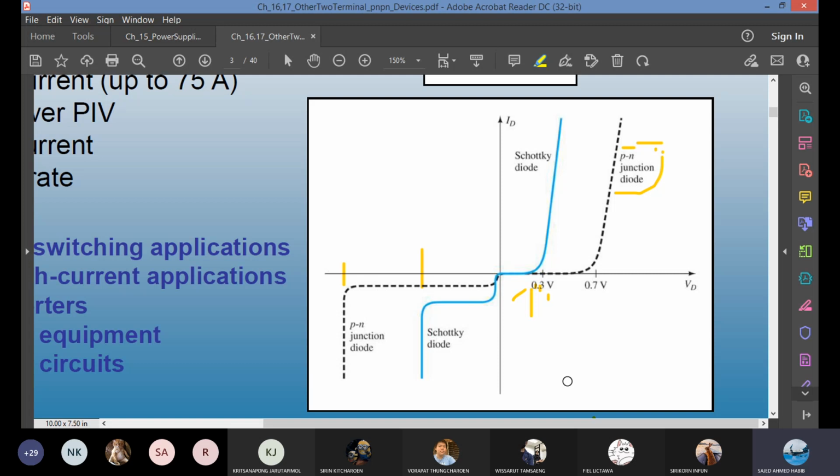The ability to carry high current easily, early. For the forward bias situation, we don't have a problem. But this ability or advantage can become a disadvantage in the reverse bias condition. You really have to watch out because soon it enters the breakdown region.